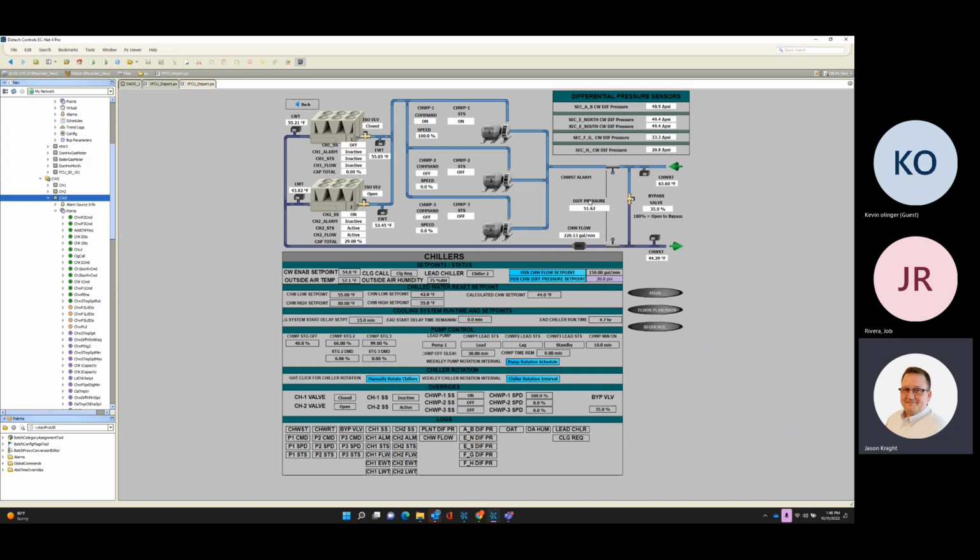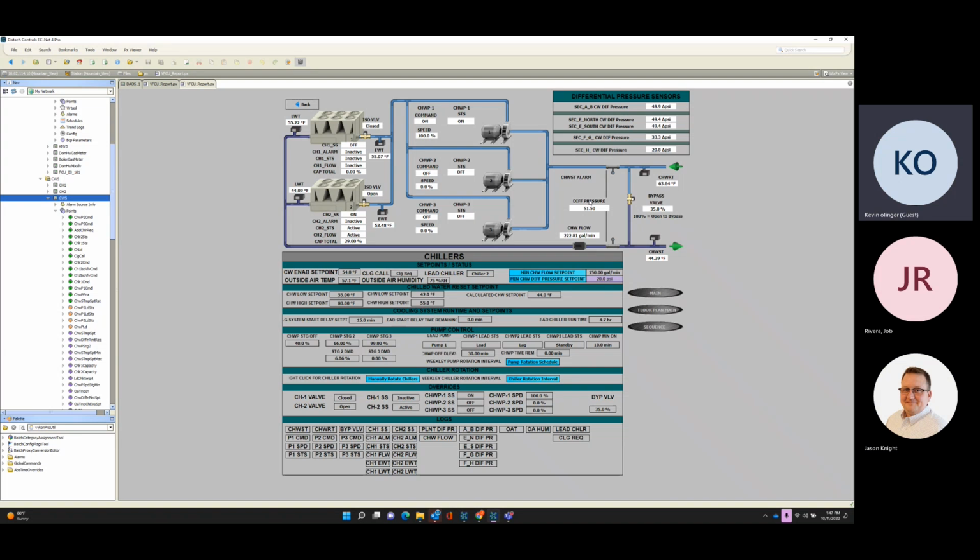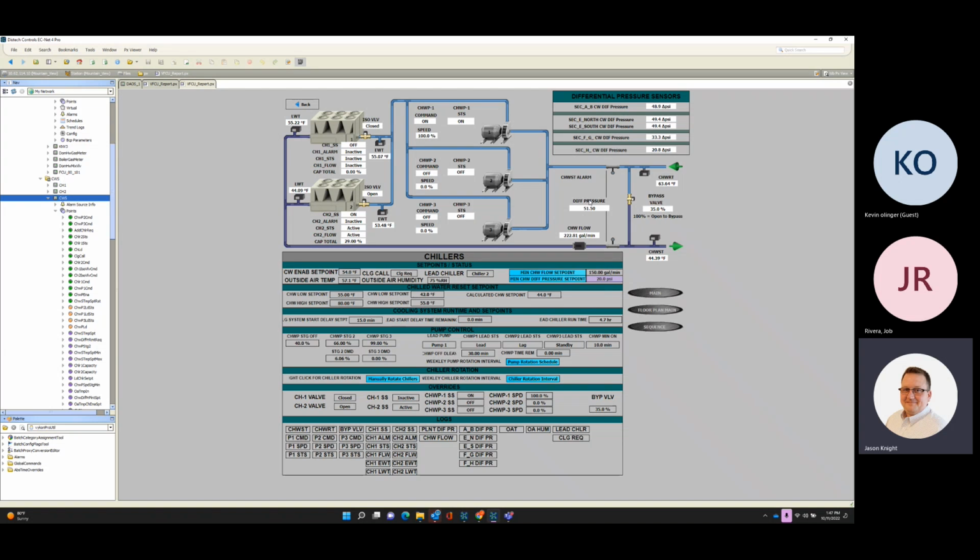Yeah. The problem that we're seeing is when the system goes unoccupied and all the valves start closing off at once, the bypass needs to react really fast because the machines still control to try and make that 44-degree water as the building goes unoccupied. And then once the air handlers start shutting off, then it indexes the chill water plant off. And then it still has its 15-minute runtime, right? Not its minimum, but its stop delay. Mm-hmm. So that's part of the problem we're running into.